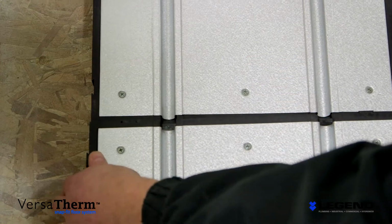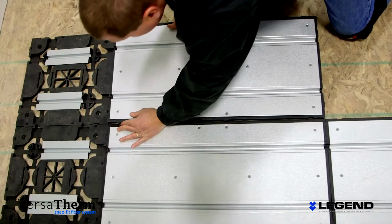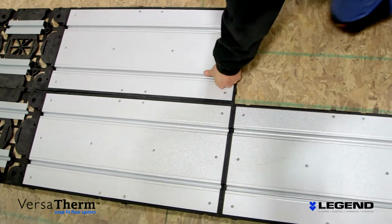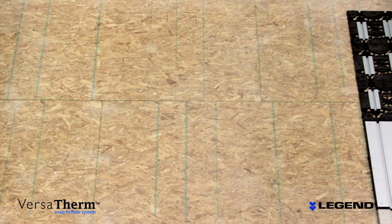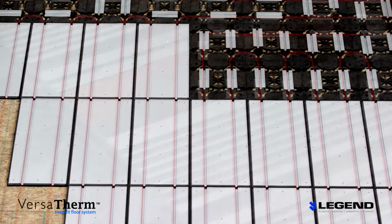Because VersaTherm panels snap together, installing the system is quick and easy. Starting near the manifold, begin laying down the VersaTherm panels. Continue by snapping the panels into place. You can lay down a maximum of 9 main panels. Use VersaTherm return panels after 9 main panels and at the end of a row. This allows for expansion and contraction of the tubing.